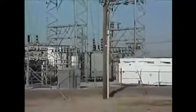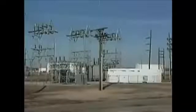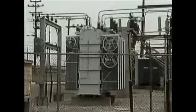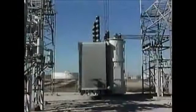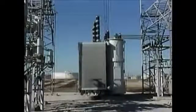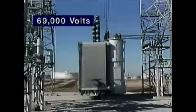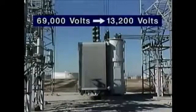For most industrial customers, electric power comes into the plant at what is known as the main substation. Voltage can be changed from one value to another using a device called a transformer. A transformer increases or decreases voltage for various uses. At this plant, the main substation transformer takes the incoming voltage, 69,000 volts, and reduces it to a level the plant can use, which in this case is 13,200 volts.